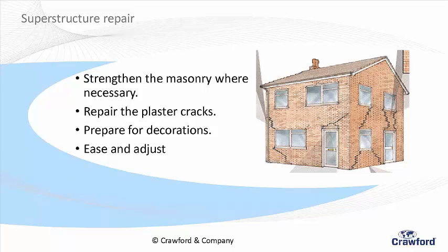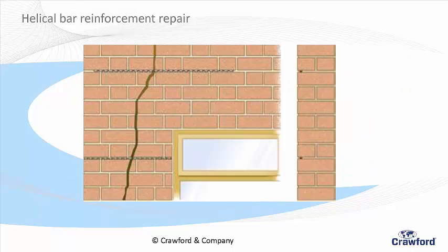You don't gain anywhere. You can put in some spectacular things like helibars, and here I've got one here. It's about the only thing I can carry in the tube. I'm not really ready. That's a helibar. I didn't want to carry the auger around with me. It's basically a helical steel bar, and it's grouted in at this section and that section in a bed joint of brickwork.